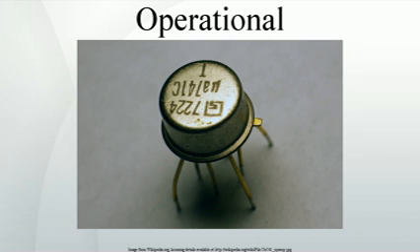Recent trends. Recently, supply voltages in analog circuits have decreased, as they have in digital logic, and low-voltage op-amps have been introduced reflecting this. Supplies of ±5 V and increasingly 3.3 V, sometimes as low as 1.8 V, are common. To maximize the signal range, modern op-amps commonly have rail-to-rail output. The output signal can range from the lowest supply voltage to the highest, and sometimes rail-to-rail input.